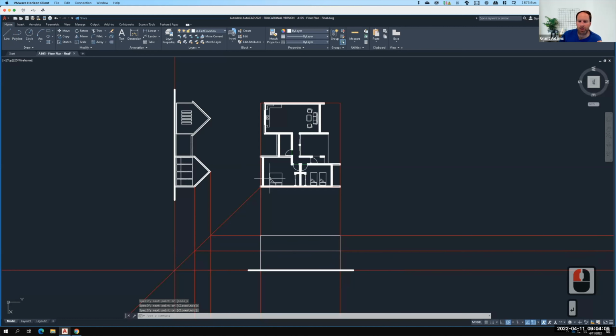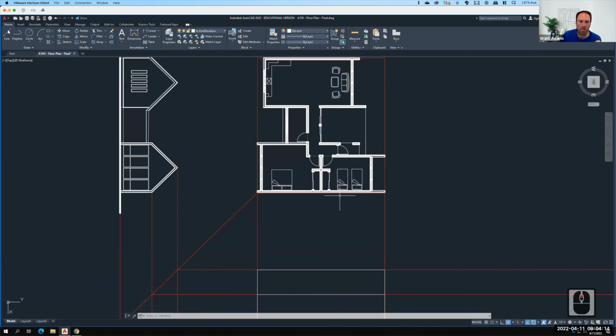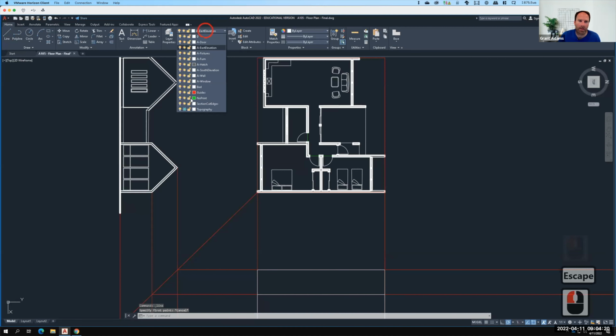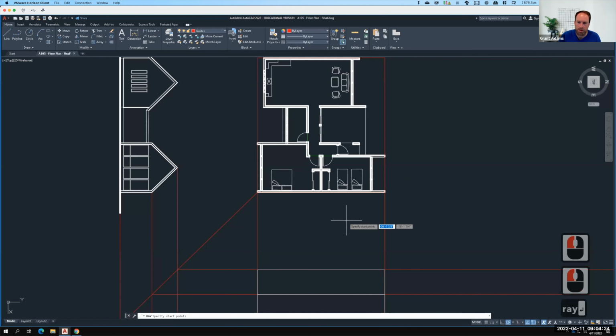Now there's no windows on this wall, which is nice, but there are these little overhangs. So I really need some dotted lines to represent those overhangs. So let me do a ray. I'll switch to the guides layer. I'll type ray. And we come down there.